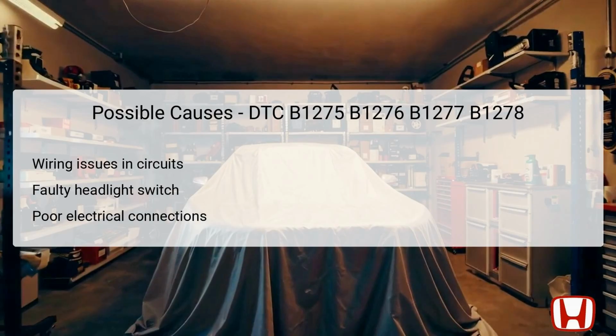Lastly, poor electrical connections can hinder the communication between the headlight switch and the vehicle's electrical system, often necessitating checks of circuits for loose or corroded connections.